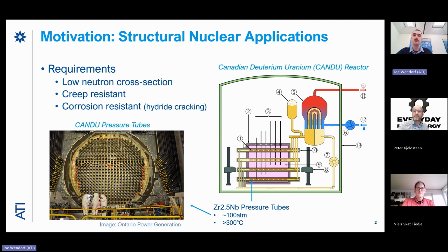Yeah. So these tubes hold this water under very high pressure. It's about 100 atmospheres of pressure in order to raise that boiling point, right? Just like if you go up on Mount Everest, the boiling point of water goes down. Well, if you go to really high pressure, the boiling point goes up. And so the water is a liquid at these operating temperatures, and it can pull a lot more heat out of the fission reaction than a lower temperature coolant loop.